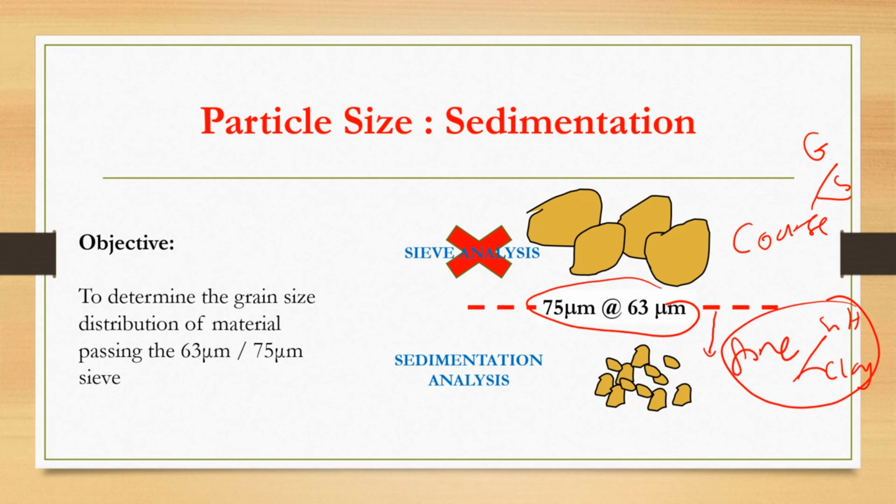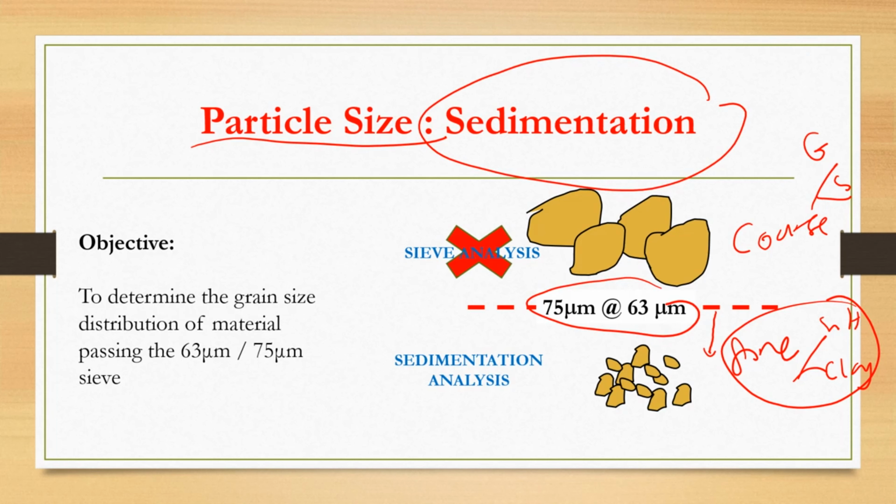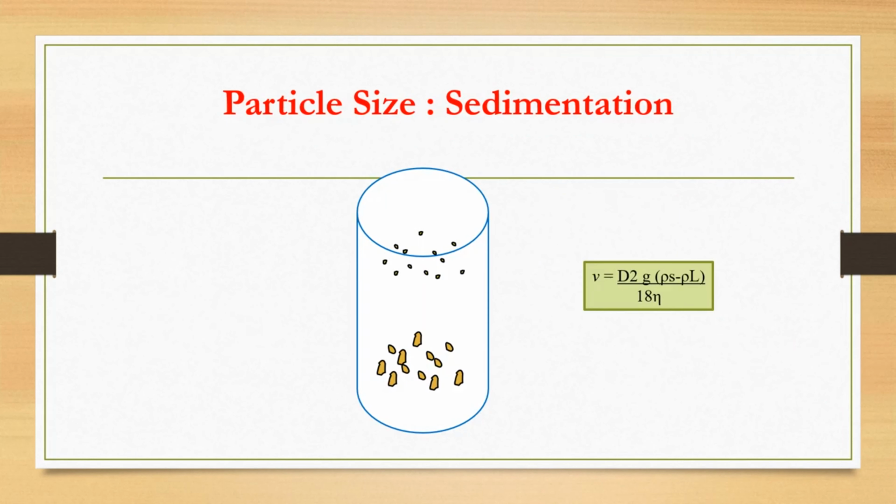So this fine grain soil group contains particles that have charges, where they have the ability to stick together. So by sieving, it is quite difficult to separate them, and quite difficult to get the individual particles. Therefore, the other method based on particle size to determine and classify the soil is sedimentation analysis, also known as the hydrometer test. The behavior of small particles in liquid suspension that have a tendency to settle down due to multiple forces acting on them is known as sedimentation.